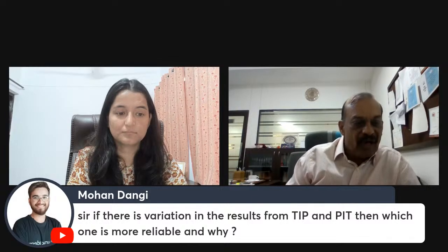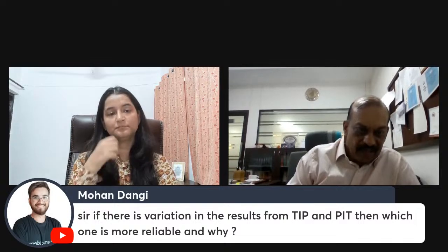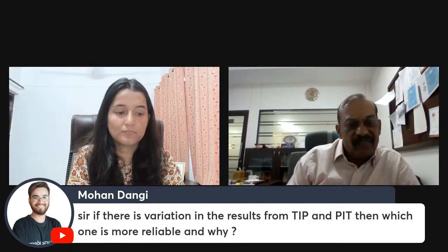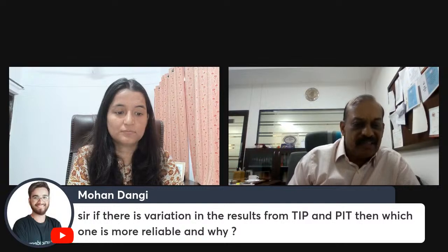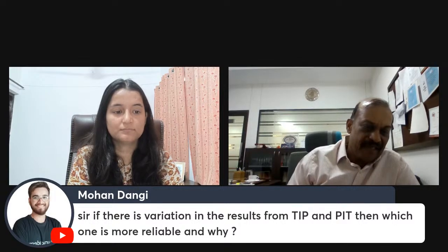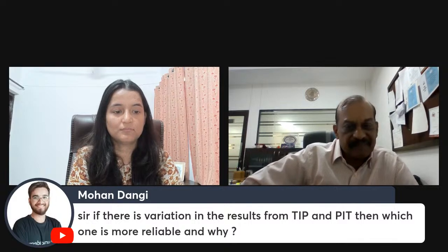Maybe you want to even do a static load test, and figure out if that pile can still be used. There may be some defects in the pile, but that doesn't mean that you have to reject the pile. If the pile is still able to carry the load, it's fine with minor defects.